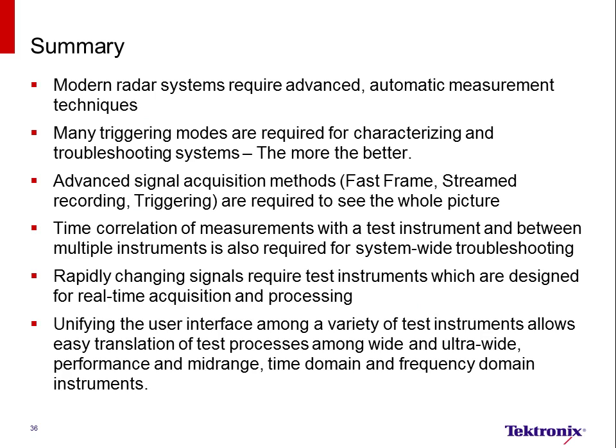So in summary, modern radar systems require advanced automated measurement techniques. Many triggering modes are required for characterizing and troubleshooting systems. The more, the better. Advanced signal acquisition methods, such as fast frame, streamed recording, and triggering are required to see the whole picture.